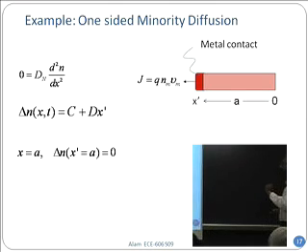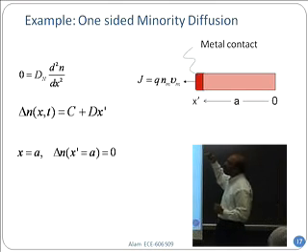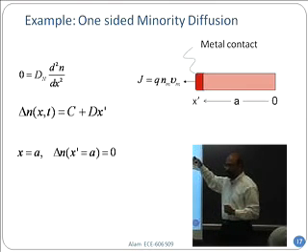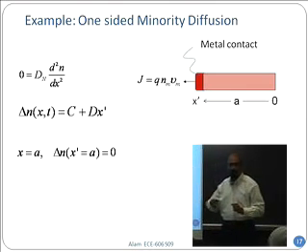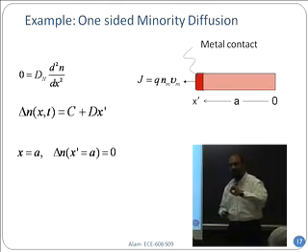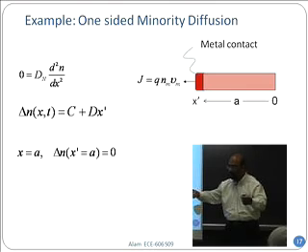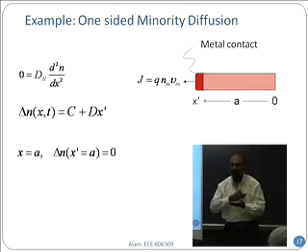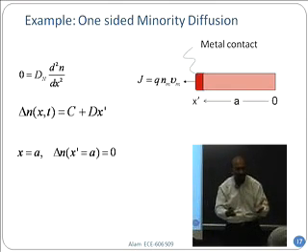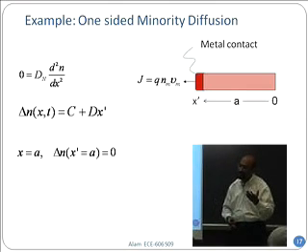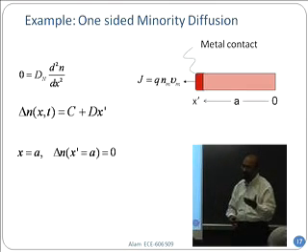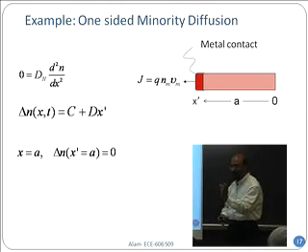The reason is, once the electrons get out of the semiconductor and get into the metal, metal has very high mobility. Electrons go very easily, right? When you have a copper wire, put a voltage in it, doesn't a lot of current flow? So electrons have very high mobility and very high velocity within the metal. Now, if it has a very high velocity, in order to support a certain amount of current, how much delta n would you need?